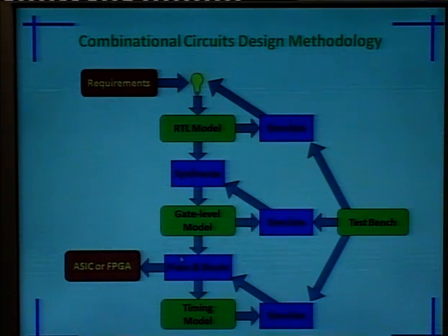Placement and routing is nothing but placement, which module we have to place where. For example, in structural modeling we have 4 modules: OR gate, AND gate, half adder, full adder. If those different components are there, which component should be placed nearest, so that our communication has minimum delay and minimum path.